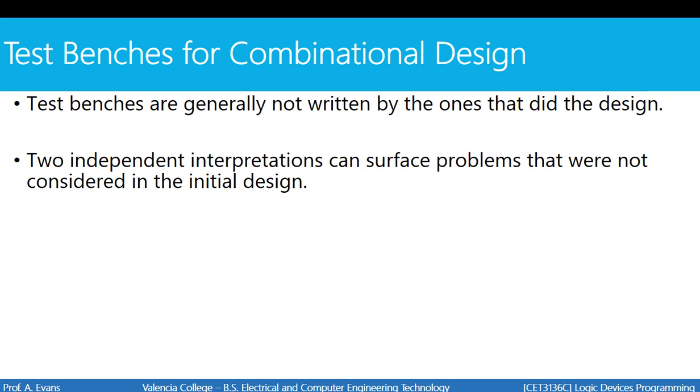And then you would go and write a test bench for the half adder, not knowing how someone else on a different team might be writing the code to actually implement a half adder. And that way you actually have a second set of eyes on the project. If the person writing the code is also the person testing it, they may have some blind spots that they're just not aware of. So by having those two ideas, testing and design, separate, you actually have a stronger method for verifying what you're building is actually going to work as designed.